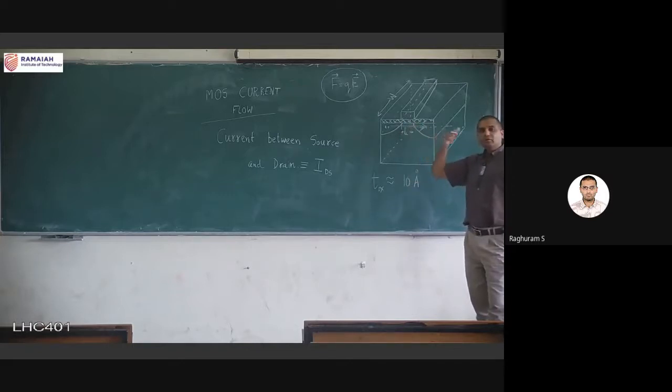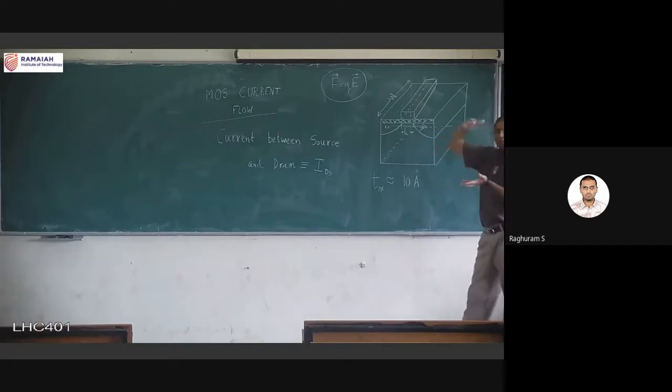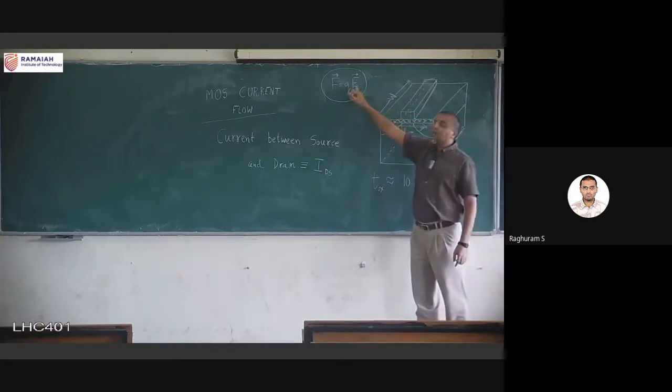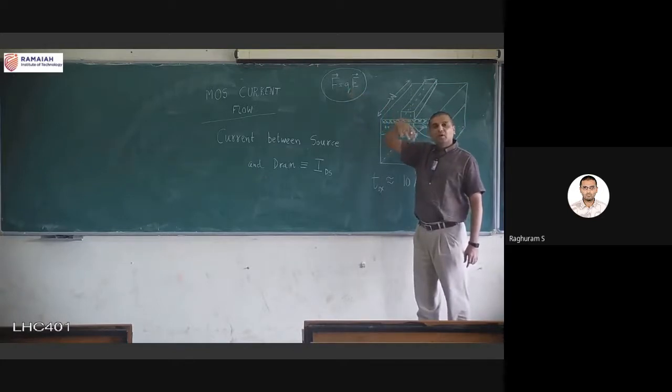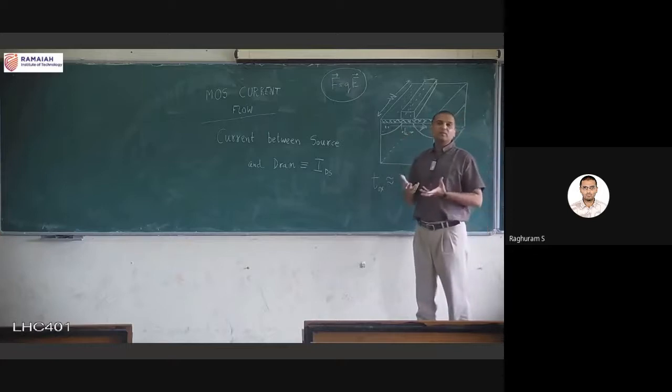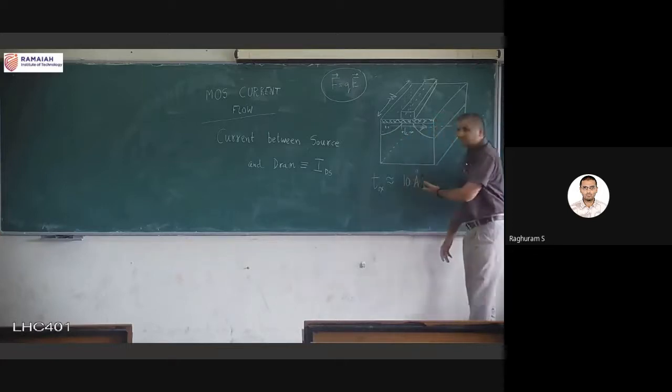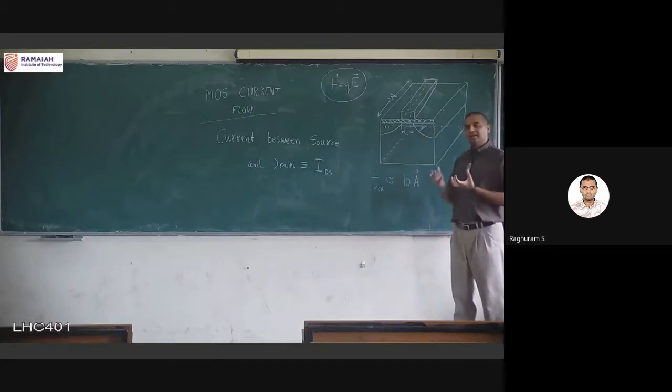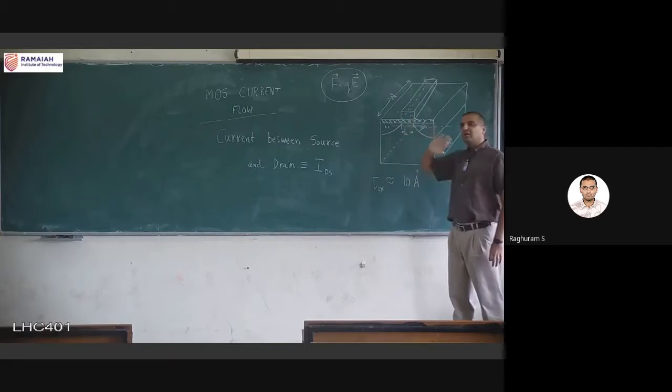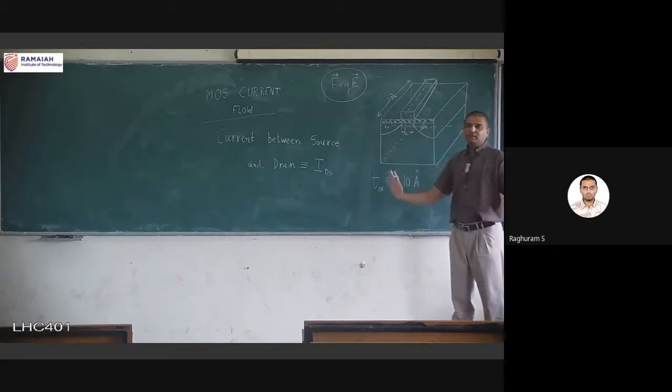Again, previously also we explained, if it is too thick, then the electric field cannot penetrate the oxide and reach the substrate, so it will not be able to attract any electrons. So if it is at a very, very low value, then the chances of attracting the electrons are better, it's good. And because it is very small, thin oxide, there will also be some current in this direction. That is all part of the leakage current. In all the 5 units of this course, we are never going to calculate any of that. It is there. Whenever we do the lab, you will see that there is also leakage current, which is given as part of the overall power consumption, but we will not calculate that.